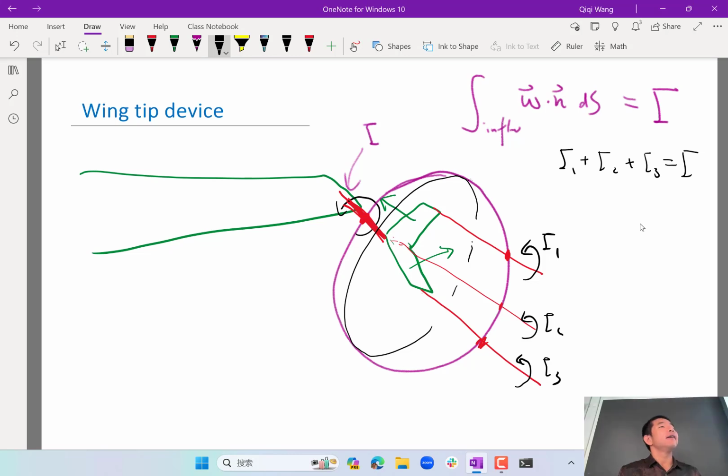The other thing is, you have 3 vortices, but that's assuming that there is no taper in the winglets, right? In reality, this concentrated vortex is not going to be a single vortex. There is a spread of vorticity along the wing, and also a spread of vorticity on this span. So what comes out is almost 3 surfaces of vortices. But these 3 locations would be where the vorticity is most concentrated.